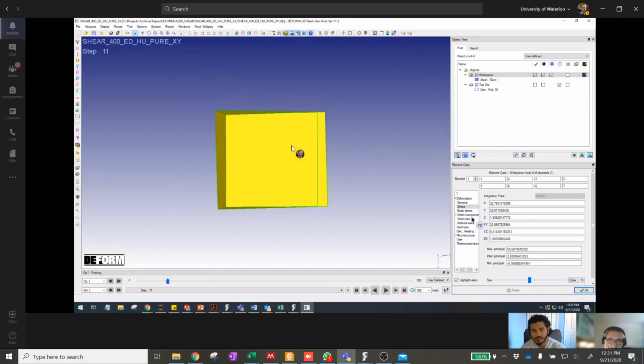But this is the problem: the two nodes that you're applying the velocity boundary condition to, it's not allowing them to move in the Z direction. The rest of the plane here has symmetry, but this node is actually not expanding in the Z direction. So it's causing stress on it, because in the process of moving it in the X and Y direction, it's not allowing it to move in the Z.